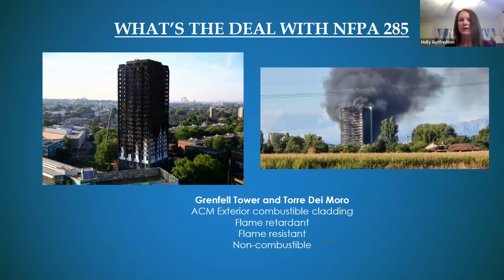Definitely, we want to talk about NFPA 285 and combustibility. I know most of us are probably familiar with what happened in Grenfell Tower. There was some ACM that had not been tested that was part of that exterior cladding. Unfortunately, that went up in flames very quickly, and a lot of lives were lost.